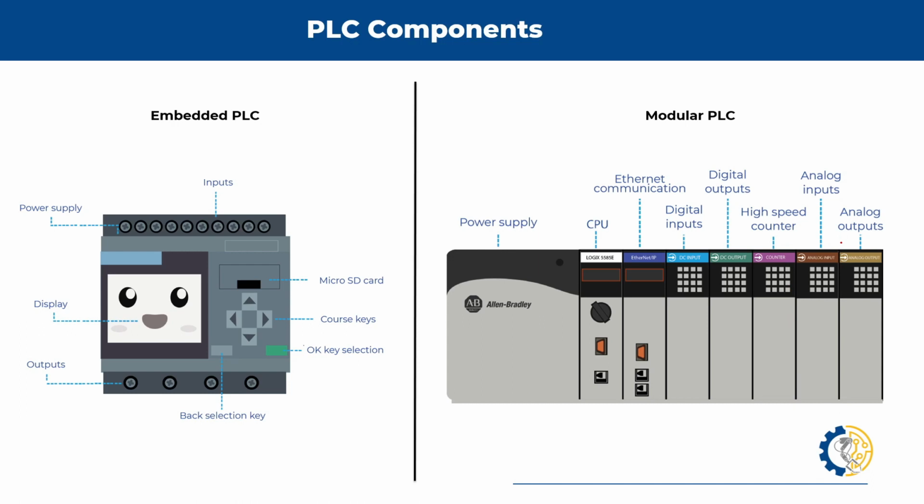If we want to assign speed, for certain velocities, we need to go gradually modifying so that we can modify the hertz and at the same time modify the velocity. So we have different modules, like for example high-speed counters, which Allen Bradley has, and Siemens also, which also have a high-speed module. And we can also connect encoders. And this is to receive data.